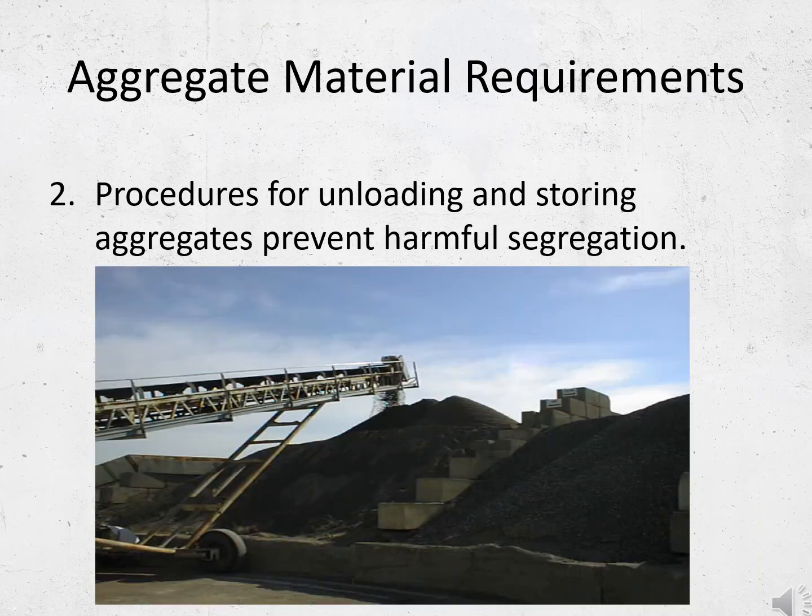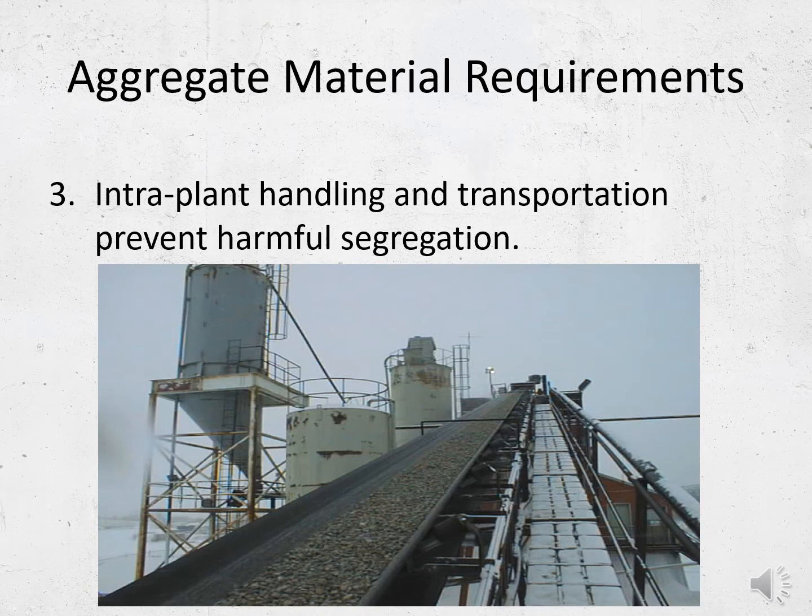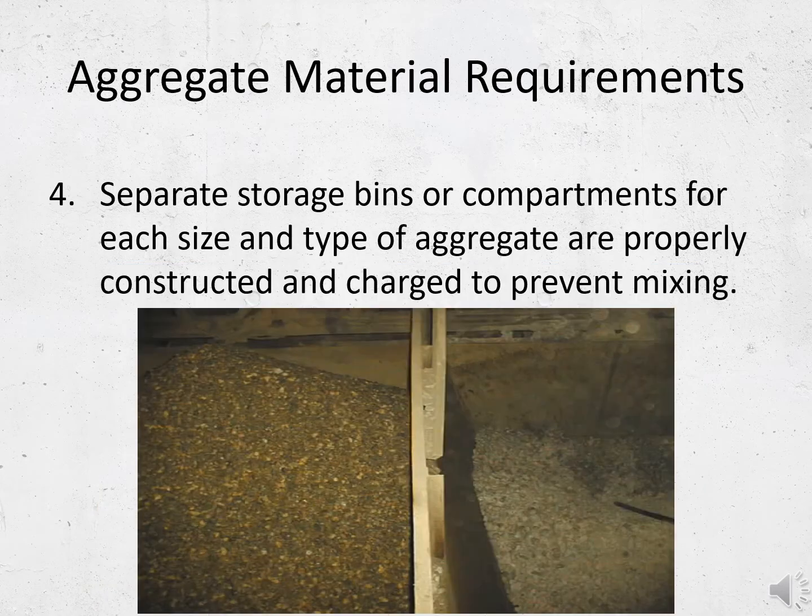If stockpiles are in the process of being built at the time of your visit, ask for a tour and ask what their protocol is for aggregate storage, and ask to see any written protocol that may exist to ensure a concerted effort is being made to prevent segregation or contamination. Ask where plant site aggregates are coming from and whether they've ever run sieves on samples from their piles to compare to the reports received from the source supplier for validation of compliance. Inspect bins for wear and charging to ensure the potential for segregation or cross-contamination is prevented.